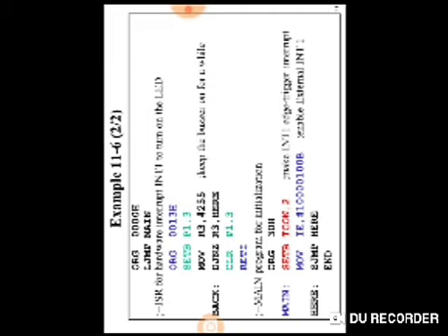Now you may see how the interrupt is going to come. Since we have activated the external interrupt, when the button is pressed in the previous figure, the active low signal will come, a high to low transition, that will make this program re-deviate to the interrupt service routine, that is 0013H. So the program goes to the 0013H location, and from there onwards the program executes.